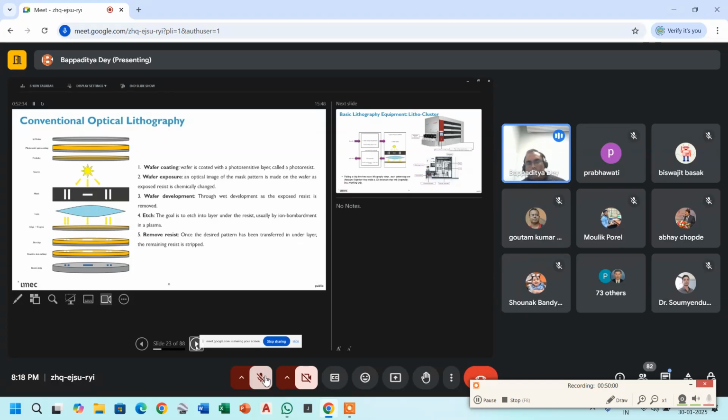This lens can capture the zeroth order and a maximum of plus minus one order. All the other higher orders, it generally cannot capture. I'll show you what the problem and the challenge are. Then you go for the final resist stripping, and you etch or print that device into a wafer, and then you can chop a chunk. You do the packaging, and the chip is ready for further electronic device usage.